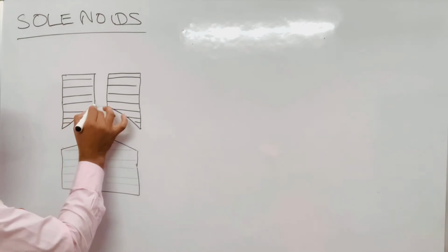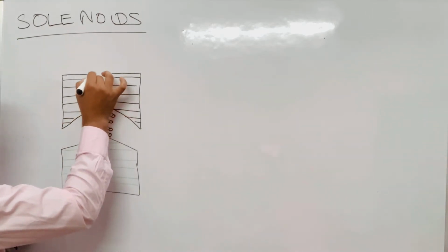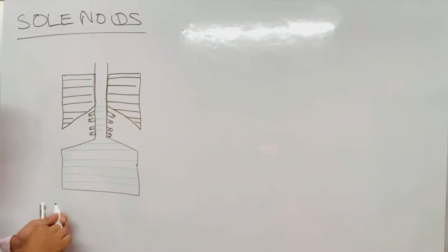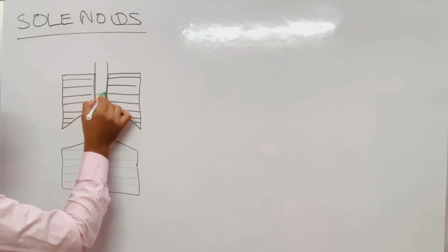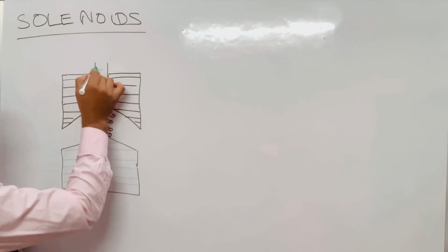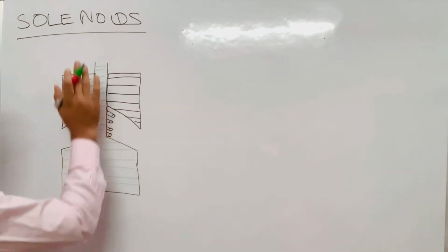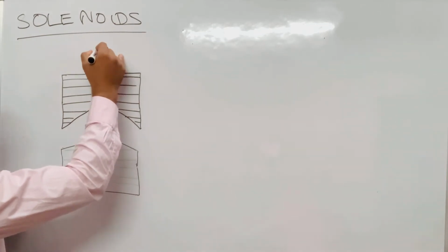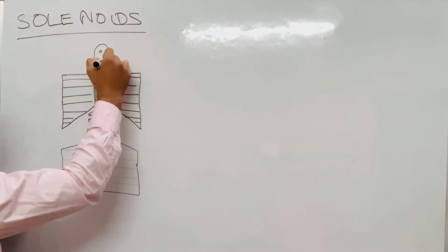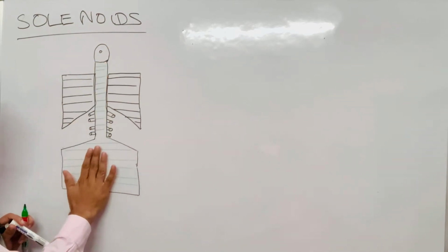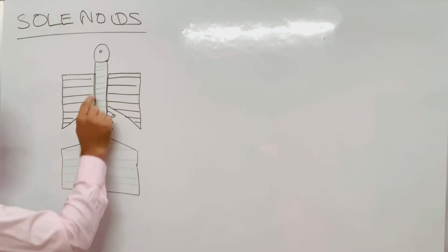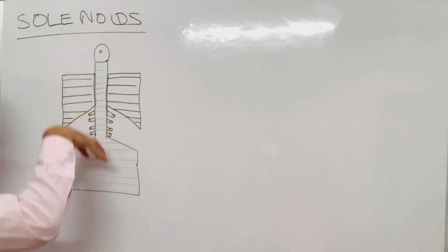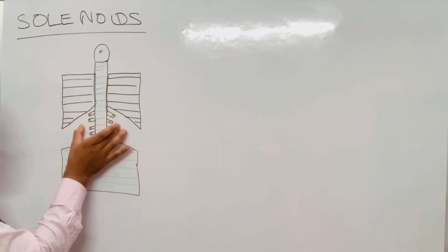So this is a control rod. A rod is there. This control rod is used to connect the movable core to the external side. Suppose here there is some mechanical linkage which I want to connect. This part, on which I have drawn the green lines, this core can move up and down. In the normal state the spring will push it downwards. That means the spring force dominates in the normal condition.